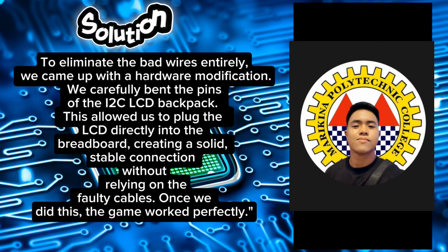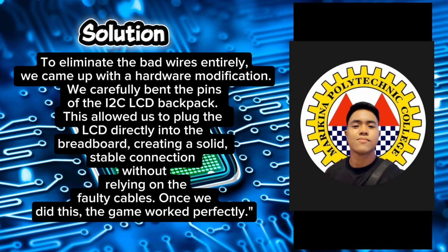The solution: to eliminate the bad wires entirely, we came up with a hardware modification. We carefully bent the pins of the I2C LCD backpack. This allowed us to plug the LCD directly into the breadboard, creating a solid, stable connection without relying on the faulty cables. Once we did this, the game worked perfectly.